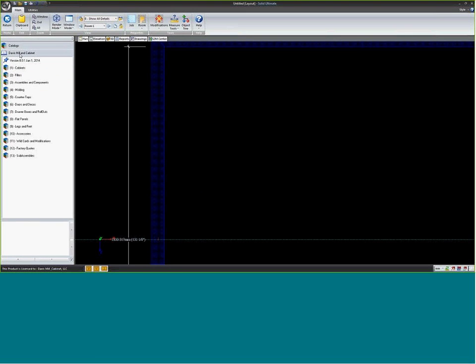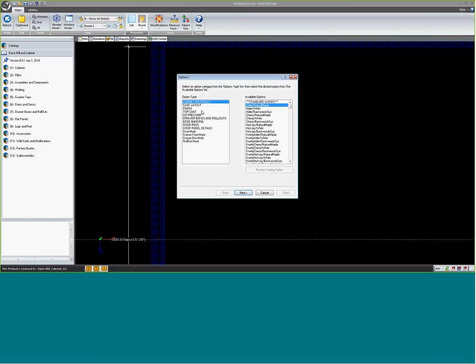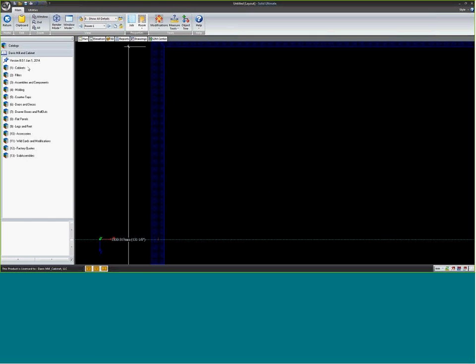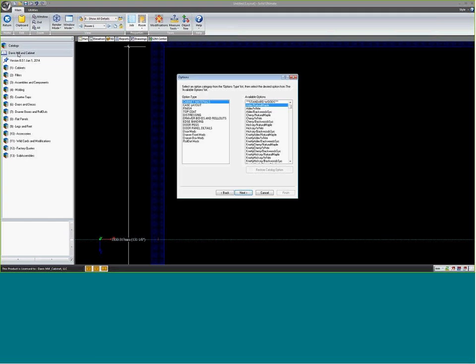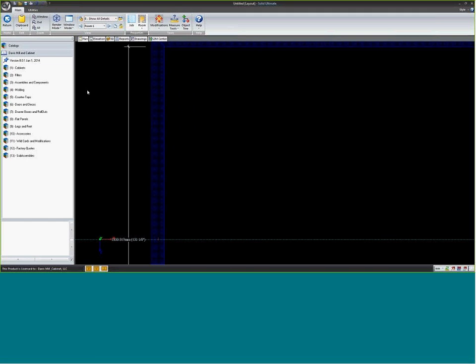So back up in here, notice when I drill down in the catalog and I want to go back up, I can either go back one step at a time like that, or I can just click back on the main catalog. One other thing about this main catalog here is if I want to access the room properties again, change the wood or door style, there are 2 ways I can do that. At the room button, if you notice there's 2 parts to this button, the bottom half will have our catalog. That brings this window up. I'll hit here, or I can come here and right-click on our catalog there, and that brings it up. So either works.